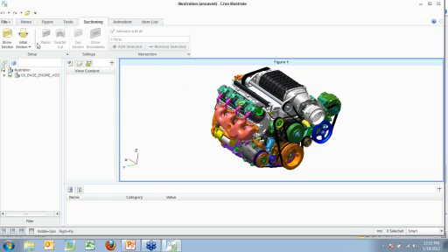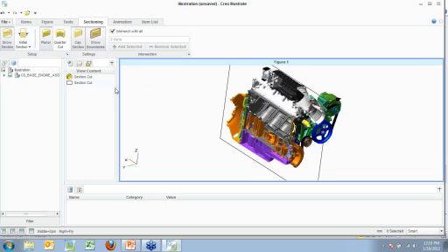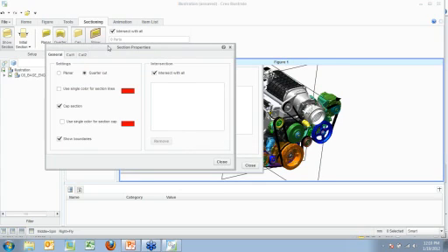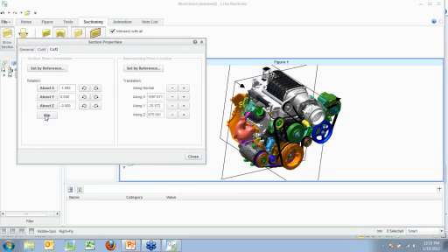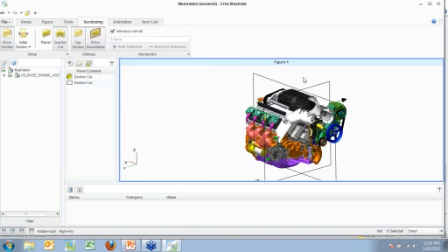These are real quick, dynamic, and easy to adjust. We'll show a section, initial section. We'll say we want this to be the Y plane. You can do quarter cuts. Simple, go in here. If that's not exactly what I'm looking for, pick the cut that I want, cut to, and I can flip it. These drag, so they're really easy to adjust to get exactly what you're looking for.